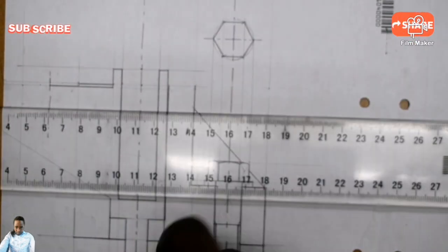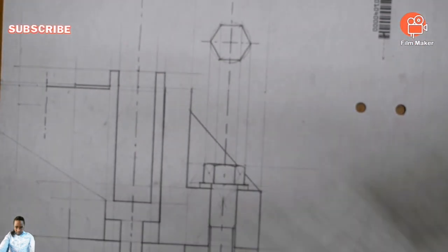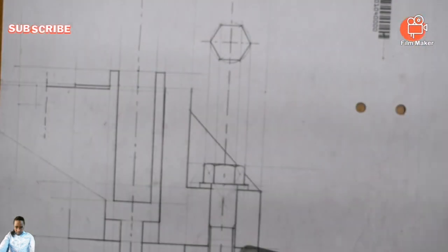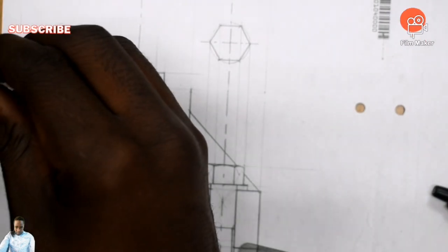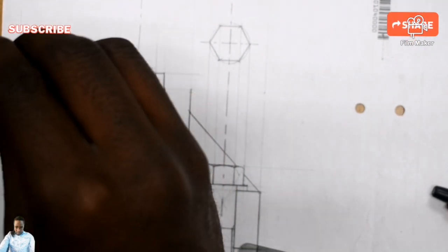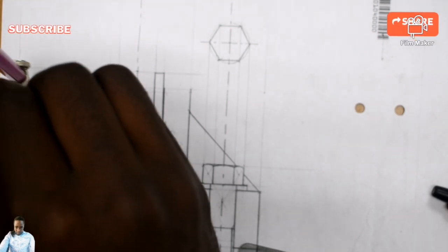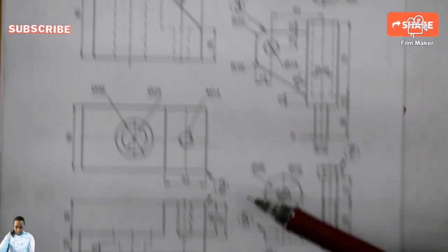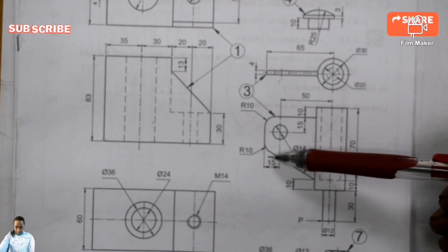Then from there, I can have a faint line, end here, and a faint vertical line. Where these two faint lines are perpendicular to each other, that's where I'm going to place my drawing compass, open it to this point, and draw a radius 10. So the radius 10 millimeter that they are talking about, you have already gotten it. You understand? So even this other side, radius 10.